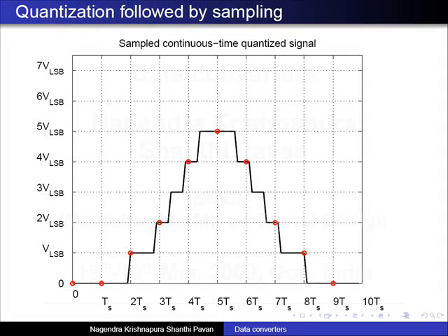What happens if I do quantization first, in the frequency domain? No, I think you are confusing. The sinc refers to the Fourier transform of a pulse, of some width. Now here the width depends on the signal. It is a nonlinear process, right? I have a sine wave, I pass it through a quantizer. What will the spectrum look like?